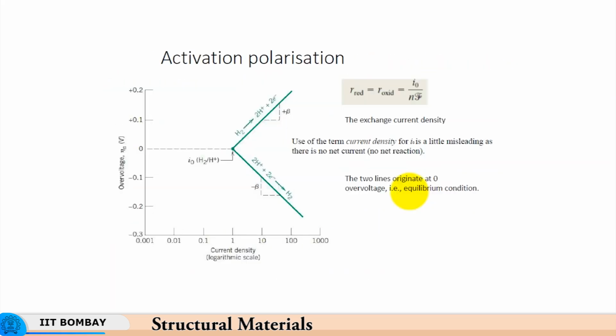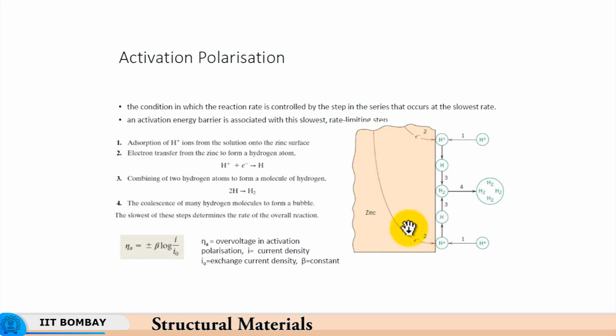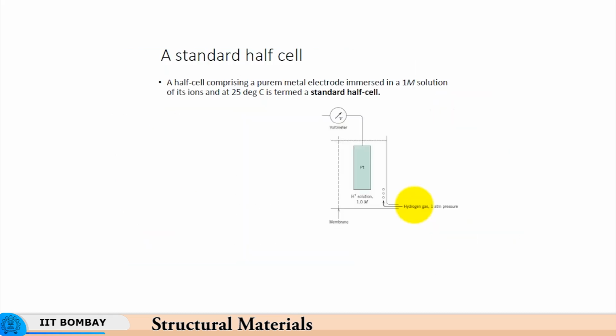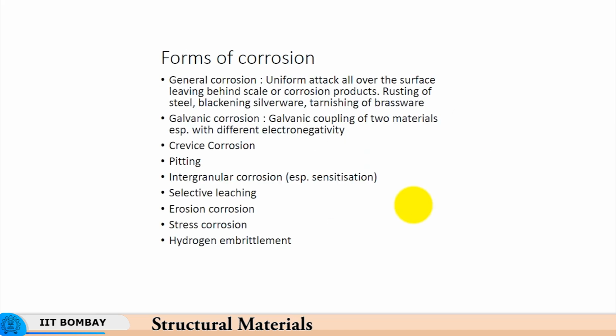Either we interfere with these reactions at anode and cathode, especially the reaction in the cathodic region, or we also render the material passive by having a film of material deposited, so that even if there is corrosive media, still the overpotential is relatively high, and the intersection of the polarization line takes place in the passive region, so that you get an extremely small rate of corrosion.